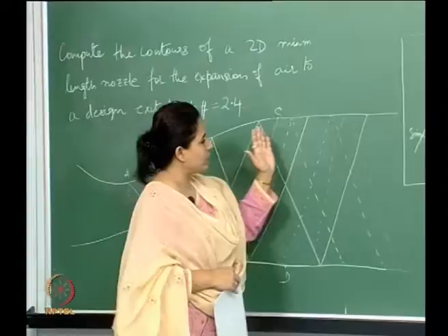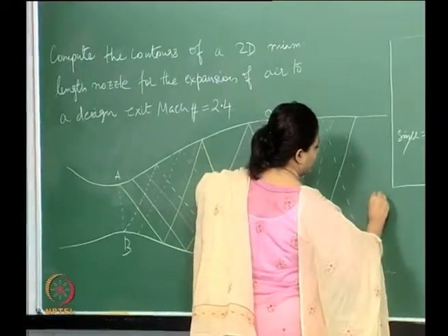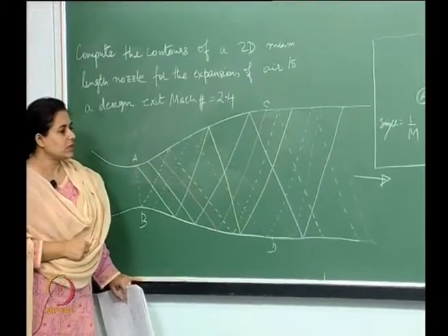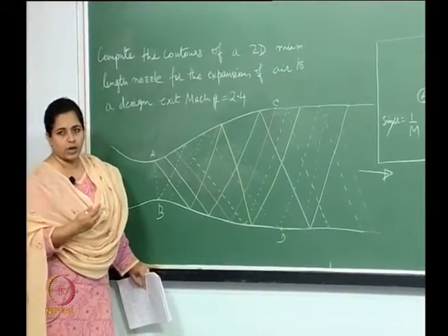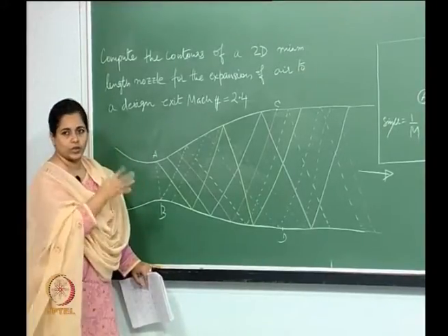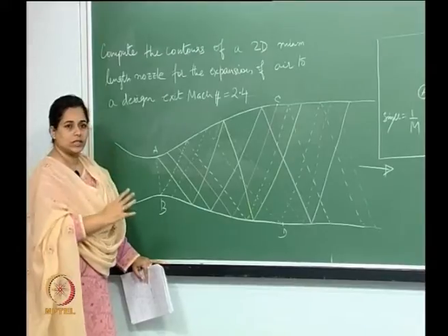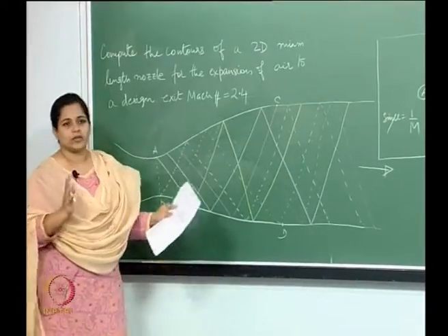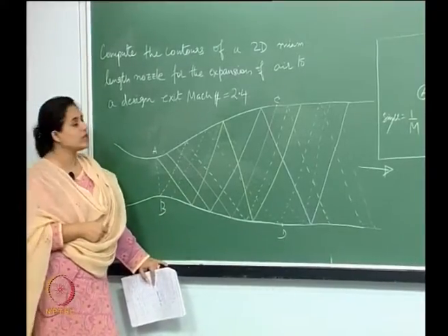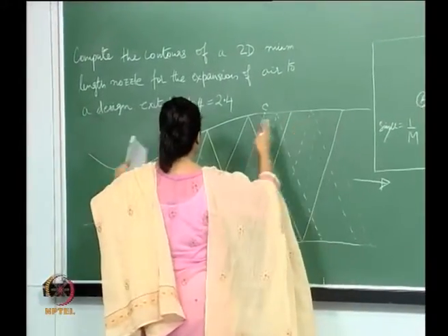Okay, here however, it becomes straight lines, and beyond this point of course, we have flow which is parallel, and that is at the exit Mach number. Okay. Now, therefore, you have supersonic wind tunnels which are going to be very long when you allow for this gradual expansion. Okay. But if you want to decrease the size of it, you want to use it in a rocket, okay, a fast moving aircraft, then what do you do? Then what we can do is essentially decrease this expansion region.